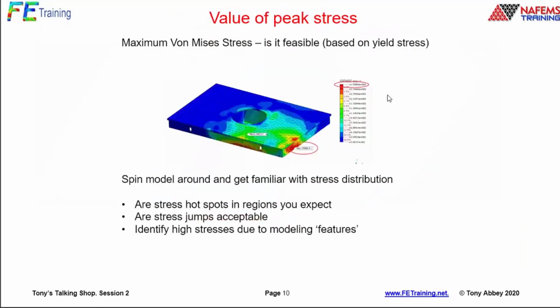Now let's look at stresses. Again, the idea is thinking of this manager's check. I'm going to look at the maximum stress, and I might as well look at von Mises stress because that's pulling everything together. Later on, I'm going to look at component stresses, maximum principal stresses, and so on. But at this point, I just want to get a snapshot of where that maximum stress is.